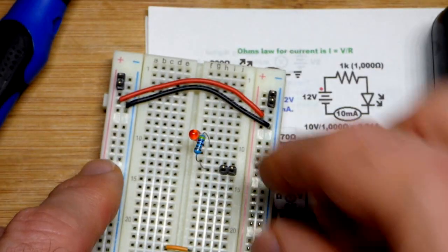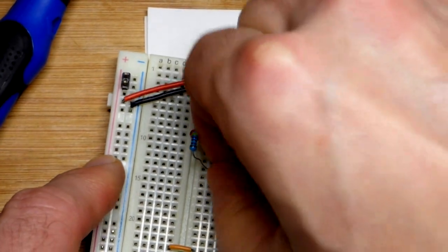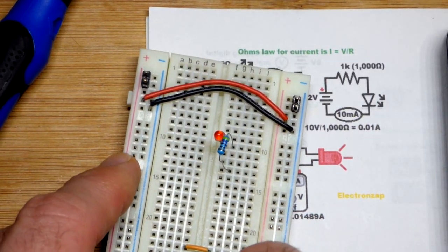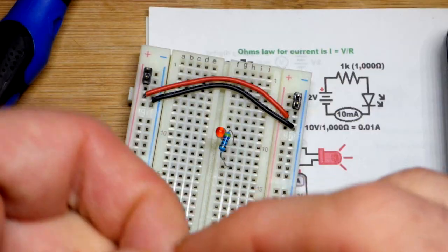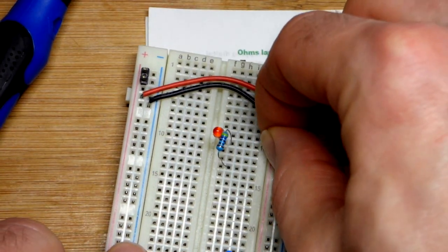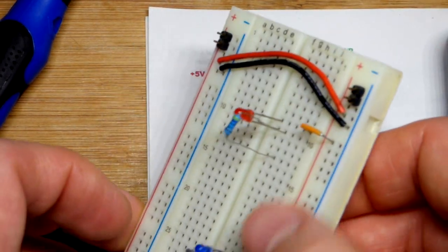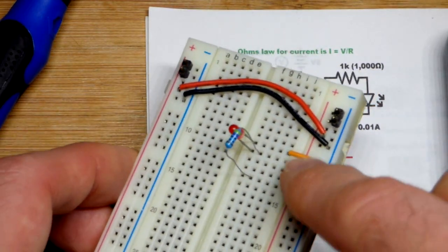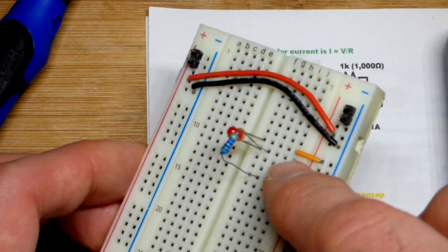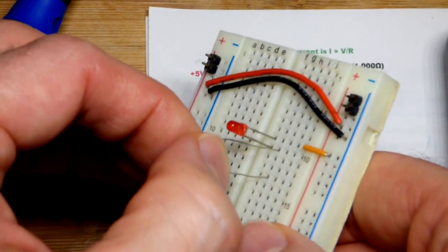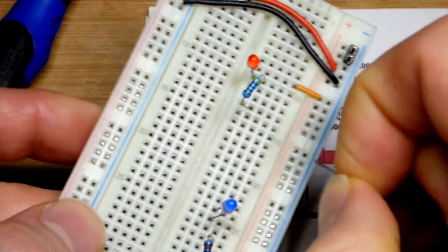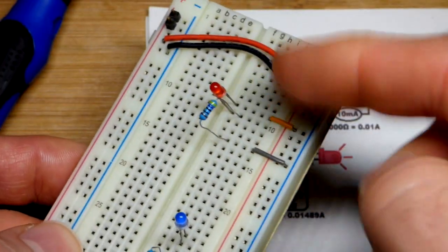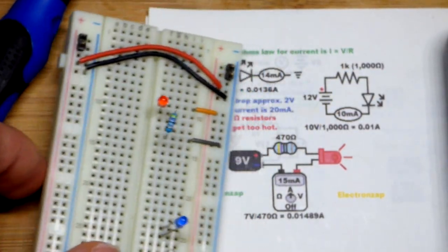So we're not going to go in depth on the color code, but that's how you read the value of the resistors. And these breadboard headers are plugged into this board a lot stronger than most things. They must be a little bit wider. So in any case, we're going to put the red jumper there. Make sure we have a good connection. As we saw before, I accidentally went to the wrong hole with my header thing, and therefore we had an opening in the circuit and it would not light up. So you want to be very careful that you wired everything properly, and then if you have a circuit that doesn't work, double check the wiring.